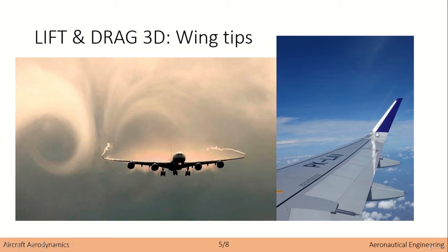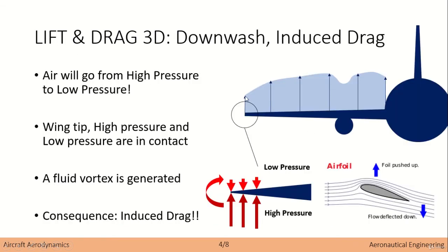And this is the idea of the definition of wingtips, okay? It's just this geometry, this material over here, which is added in order to separate the high pressure from the low pressure. And what this allows is to actually have some lift, which is the difference of pressure, as you know, which is different from zero, okay, even at the wingtip, right?